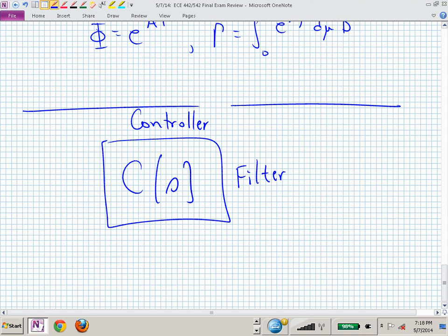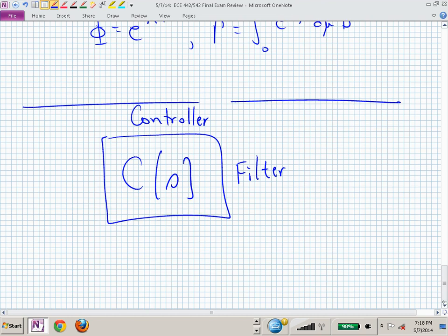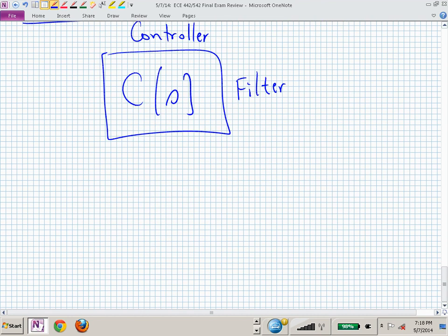Now you don't do a zero order hold equivalent because now you really have a signal coming in and a signal coming out. You're not really trying to control anything directly. You just want to preserve the behavior of this C of S with your discrete implementation. Here is where you would do either the numerical integration or the pole zero mapping approach with the discrete equivalence.